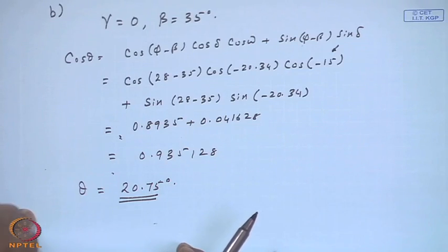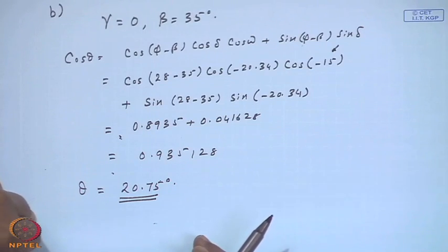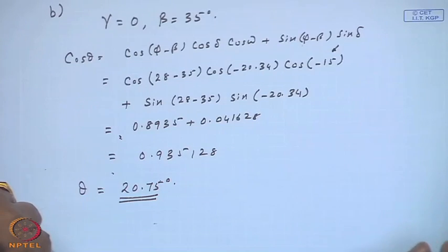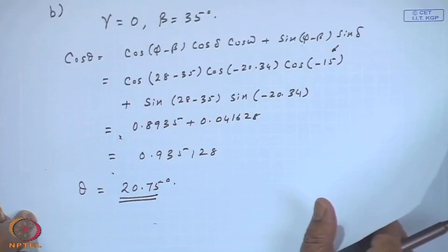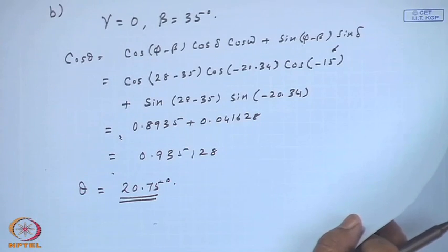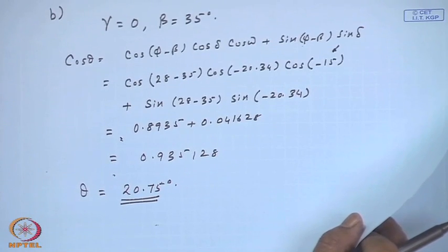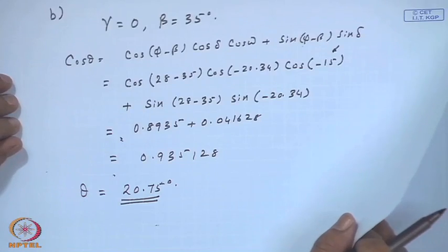So, you have got gamma equal to 0, south facing, ideal, and at 11 o'clock, almost near solar noon. We have chosen phi minus beta to be about minus 7 degrees, and that is a good orientation that one can have for your negative declination.